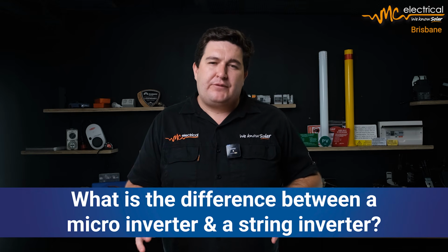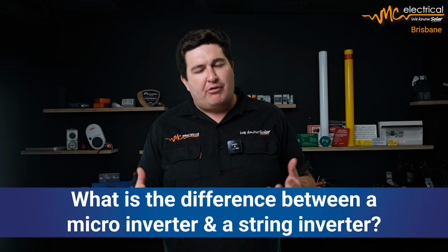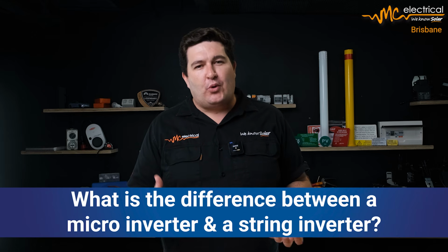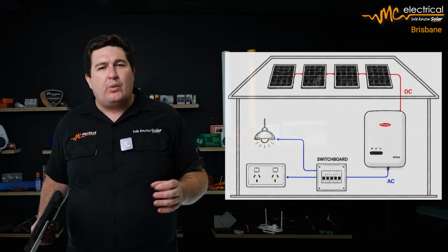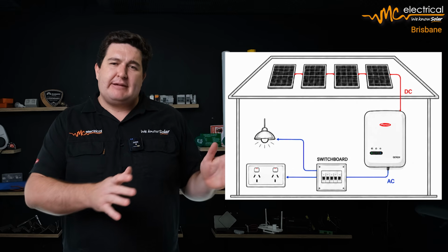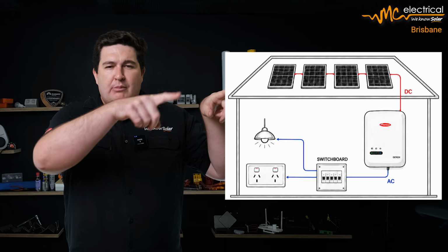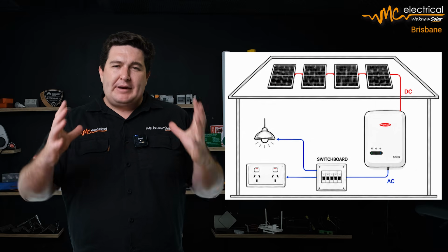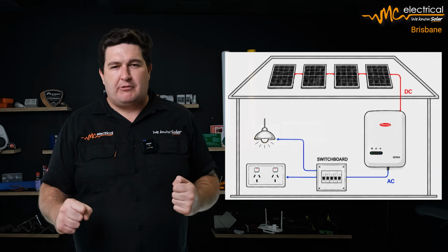You might have heard that there's a few different types of inverters, but the primary two types of inverter are a string inverter or a microinverter. Now, the one that I showed before is a string inverter, where all the panels are connected in series. So it's almost like fairy lights. They're connected positive, negative, all in one big row. And you have one inverter for the whole solar array.